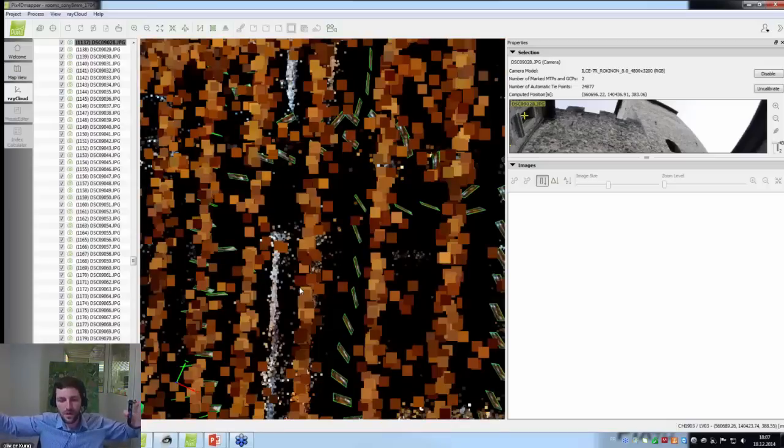So if you had to do a very big room like a theater, I would go one circle very close to the walls to make sure that you capture as much detail from the walls as possible. And then I would also make a few paths more centered around, for example, the seats or whatever is inside, to capture more details on the inside there.